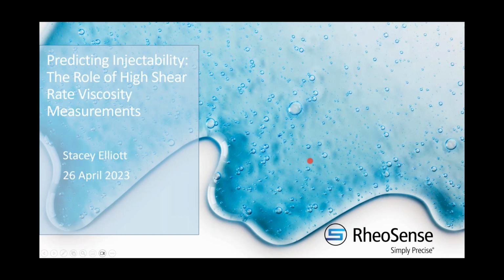So this force is basically what is it going to take to push this piston so that we can initiate and then sustain flow through our syringe. And so what's going to be important then is knowing what sort of flow you want to deliver. This is going to be how much volume in what particular time, so volume over time. And then it's going to have two components. It's going to have a friction component because obviously there's going to be some sort of friction between the piston and the barrel of the syringe.